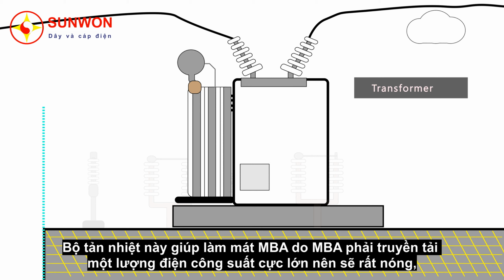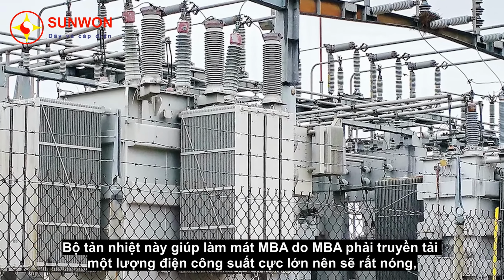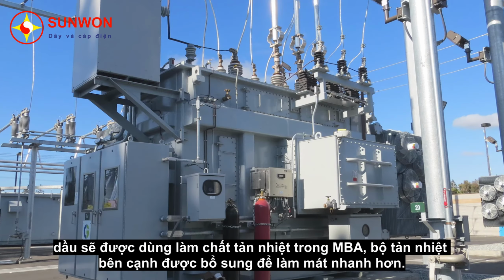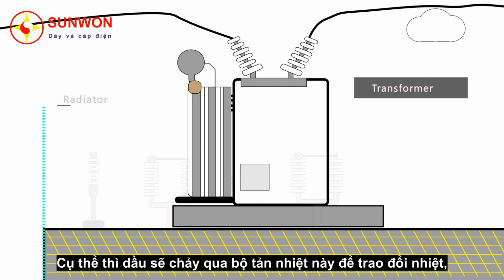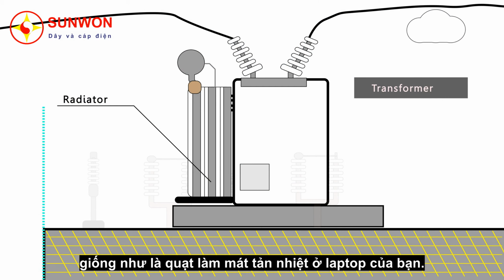The purpose of this radiator is to help with the cooling of the transformer, because transformers transfer vast amounts of energy and they do run hot. So oil is used as the coolant, but the radiator on the side is an additional measure to help cool down the transformer. Typically oil will flow through the radiator and you'll have heat exchange. You also sometimes have fans underneath the radiator to help with the cooling, just as you would in a laptop actually.